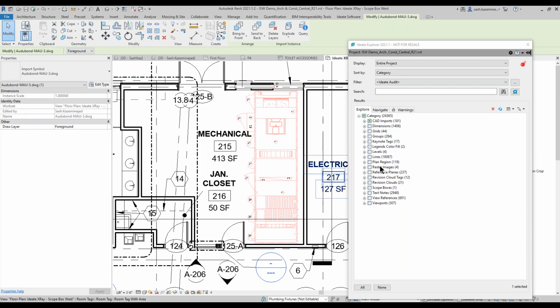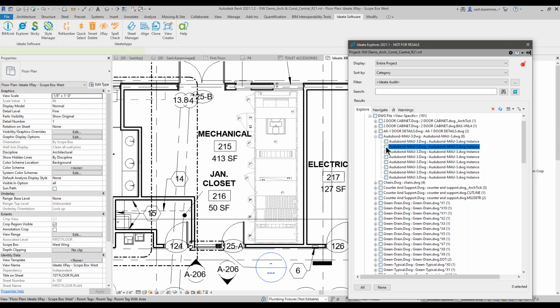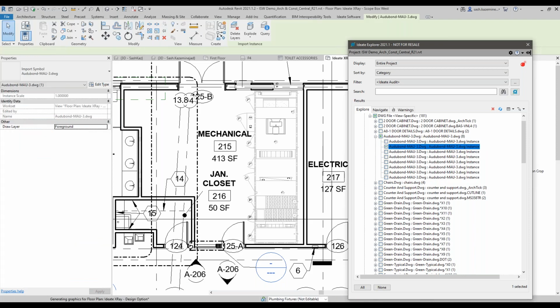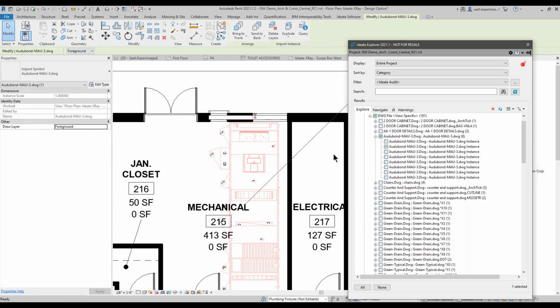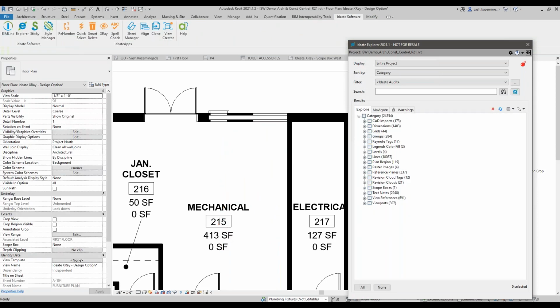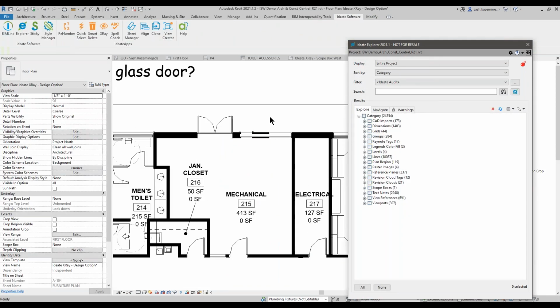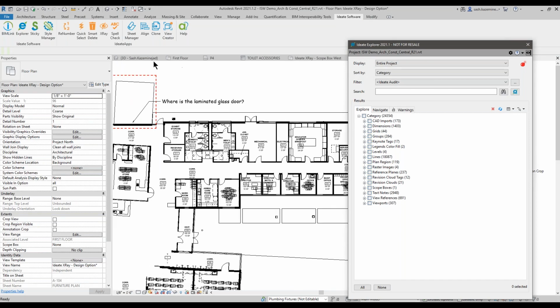And you're like, well, that's great, this works for me. But the problem is, if I come back over to my CAD imports and look at these other makeup air units and go to this view, we're going to see that there's a gap difference, right? And there actually is a gap difference. So there's no correlation between these views. Really what I should do is delete these out of the project, and if they're still using AutoCAD, at least link the DWG into the project. So be sure to really clean up CAD imports. Again, if you've exploded them, you can merge the line styles by using StyleManager. You can use Ideate Explorer to help you select some of those things.